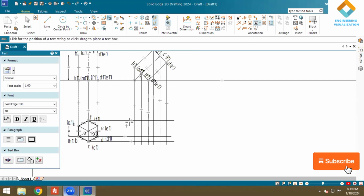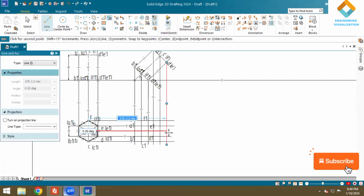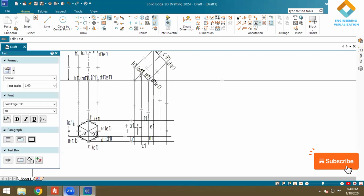So write the notation for the top view. In the top view, the bottom face is A1 B1 C1, like that you can write down. Draw a projection line from the O also. This is O1. Same way for the top face, you can write down A B C D.